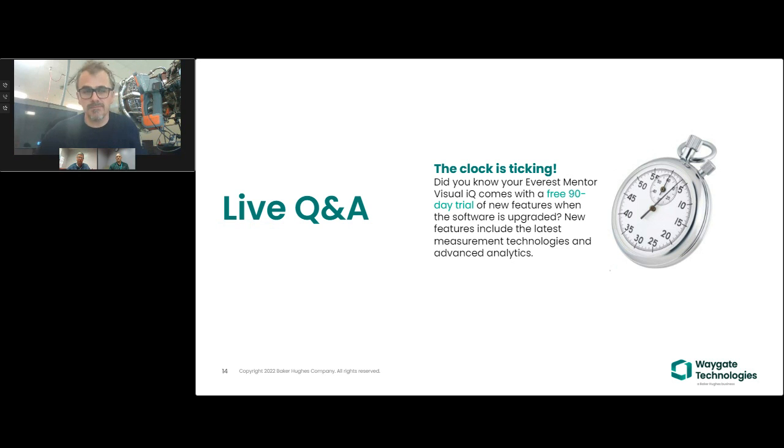That's a good one. Lots of carbon obviously sucks a lot of light out from the boroscope tip, so it'll appear very dark on your screen. So rule number one is, do you have access to a larger diameter probe, and are you using the appropriate optical tip adapter on the end of your probe for your inspection?